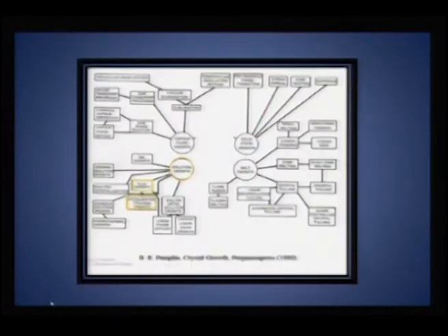So, just to conclude, we first looked at the principles of solution growth, which we are already familiar with, and then we looked at the vapor phase growth, and notably molecular beam epitaxy, which stands out as the best single crystal growth method. Then we also looked at some examples of solid state growth, and lastly we have seen the various combinations of melt growth techniques which are used even today for making fine quality single crystals.